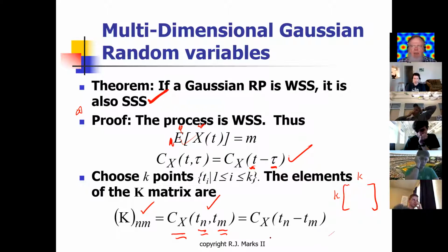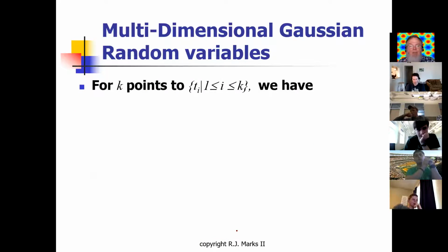But the interesting result is that the autocovariance, since we have a wide sense stationary stochastic process, is just a function of the distance between the 2 points. And that distance between the 2 points, as long as it remains the same, we're going to get the same result. And we find out for the case of the Gaussian, since we have to know the autocovariance, this is exactly the autocovariance we need to characterize the signal.